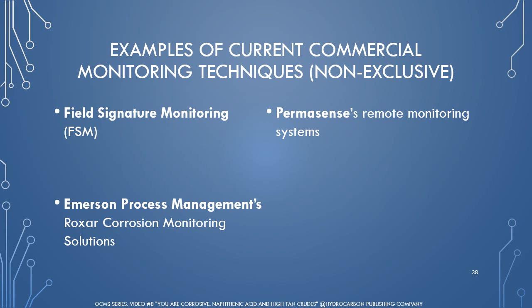This enables the refinery to identify a chemical treatment strategy that would enable it to process the crude on a continuing basis. Sensor Networks offers precision, fully digital ultrasonic wall thickness measurement systems coupled with wired and wireless data backhaul that enables semi-permanent, easily deployable corrosion monitoring systems.